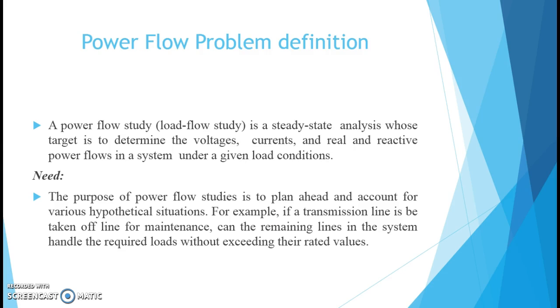Next, the power flow problem definition. Power flow study is a steady state study. Steady state means it does not depend upon time; the system operating condition is irrespective of time and is always the same.